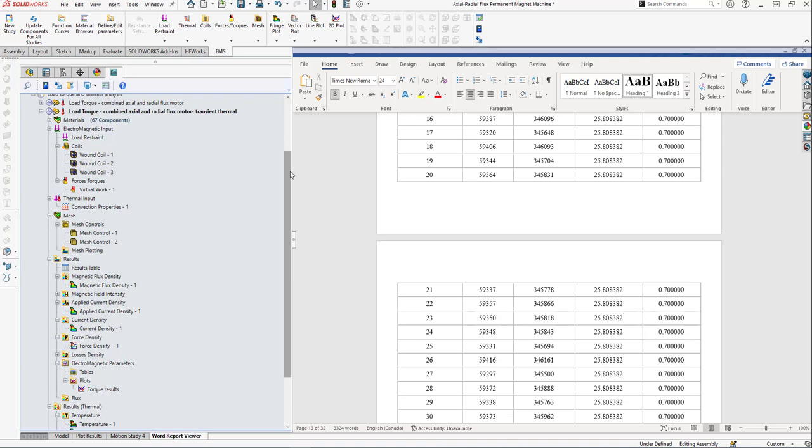the RADAX, or radial-axial flux machine, is a promising new machine that started surfacing in the literature. That's why we wanted to bring your attention to this new machine. It's still in the research phase, but it's very promising because it gives very high torque and a very high back EMF compared to either radial only or axial only. These are two very important features.